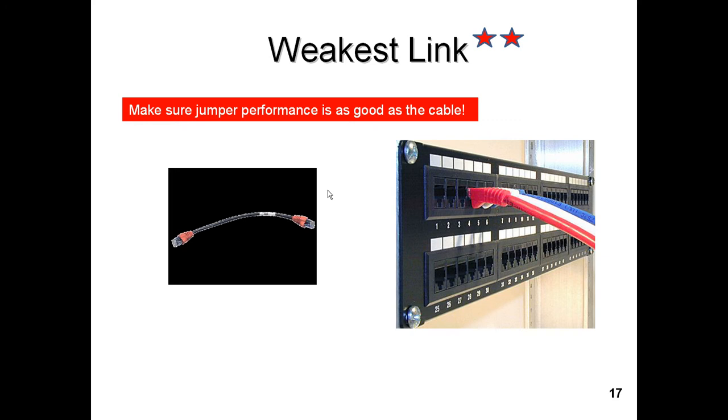Stranded conductors are built so that the cable can move around a little bit and be flexed a little bit, and the connection doesn't break. If we make our own jumpers out of a roll of Cat5e cable, well, repeated flexing, repeated movement of the cable could snap the copper conductor internally. So buy jumper cables.